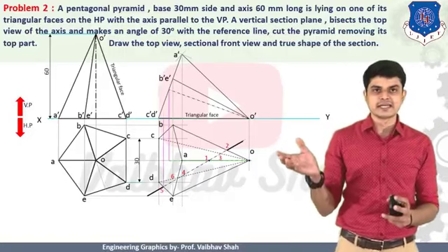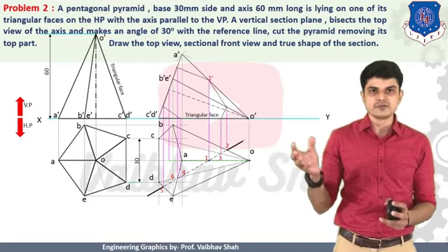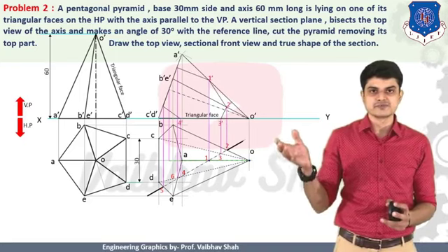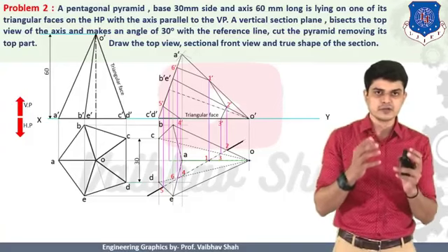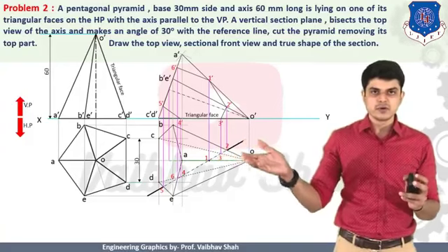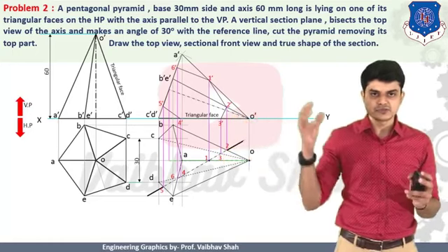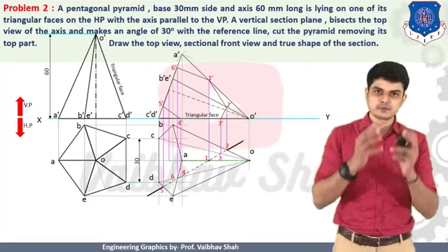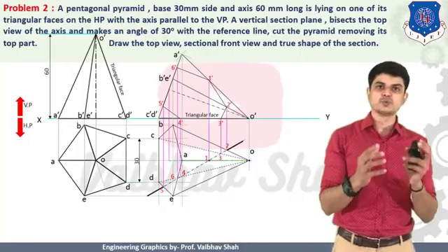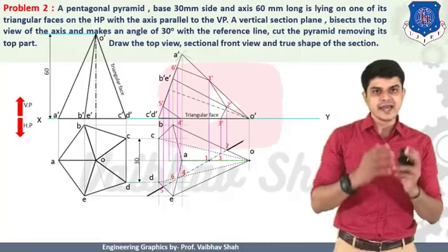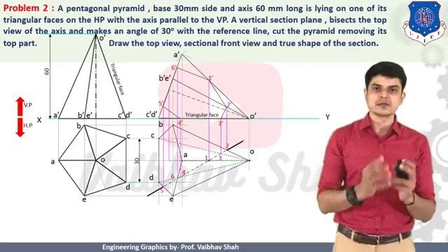And after transferring each and every point to the corresponding lines, we should join these points, giving the numbering like this: 1 dash, 2 dash, 3 dash, 4 dash, 5 dash, and 6 dash. So we will be able to complete the object generated. So let us observe, we have transferred this point 1 onto this OA line somewhere here. Then we have transferred this point 2 on OB line somewhere there. So we should transfer each of the points vertically up to the corresponding line. And after getting these points, we should label them 1 dash, 2 dash, 3 dash, 4 dash, 5 dash, and 6 dash. And then we should connect all these points by a darker line. We have this cut section generated, which is nothing but our final.